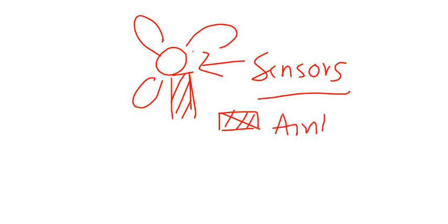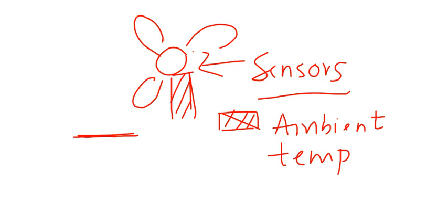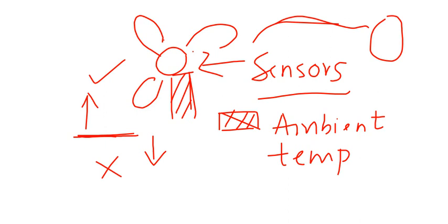Now you have some rule. As long as the temperature is below this value, you don't turn on the fan. Once it goes above this value, you turn on the fan. Now this information you would store somewhere in the cloud. You have the temperature measurement here, you connect it to the cloud and you get it back, and based on the information received from the cloud, you make the arrangements to turn on or turn off your actuator, to either turn on the fan or turn off the fan.